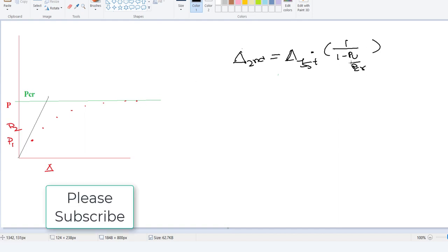So if we take this expression, you can see that if my applied load is very close or equal to the buckling load or the crippling load, then this term becomes 1. That means 1 minus 1 is 0. The denominator is 0. That means this entire expression would have an infinite value. That means the response for the second order analysis, if you are taking the second order effect, would be infinitely high.